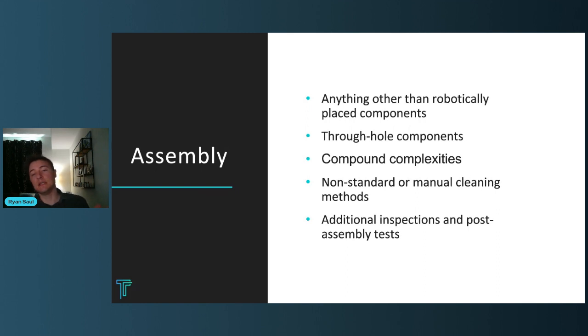Okay, another example is cleaning methods. These days, the industry is moving towards using quote unquote no clean flux, but then cleaning the boards anyway. All of your manufacturers should be washing the boards post-assembly. It's not expensive. That said, if you have elements on your board that can't go through an inline wash process, I'm talking about pressure sensors or microelectromechanical things like microphones.